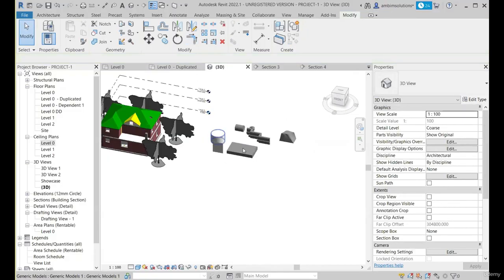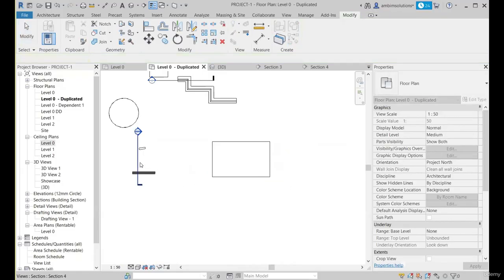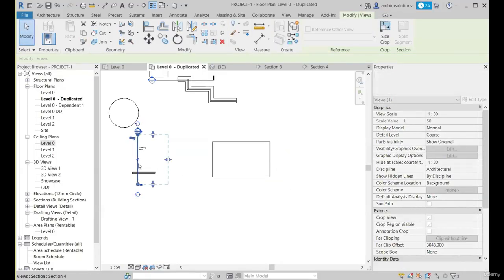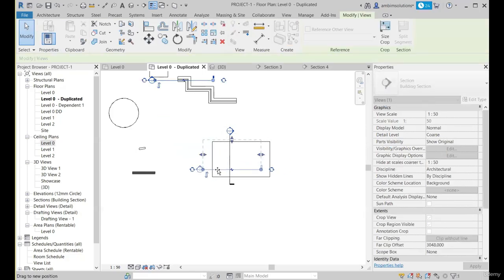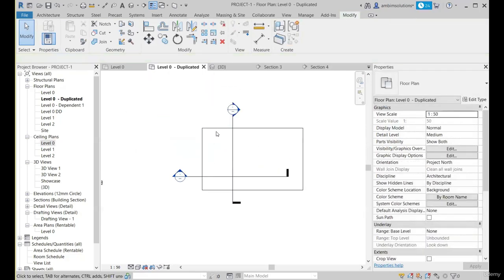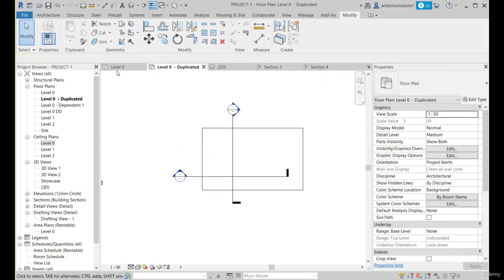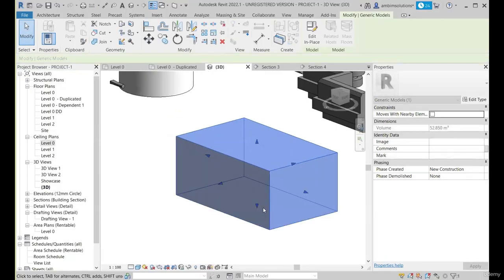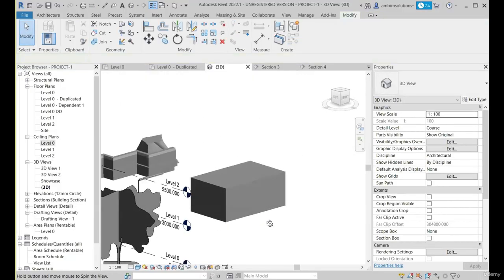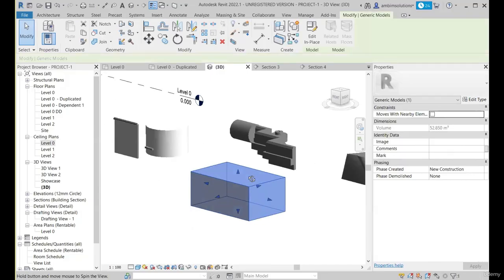Now we will move ahead, checking out the void forms. So this is a section here, and we'll have a section here as well. In order to create a void form, let's edit this only, you will understand better. Currently we have a rectangular extrusion, so let's create a big rectangular extrusion here. We'll test the void forms on the solid form.